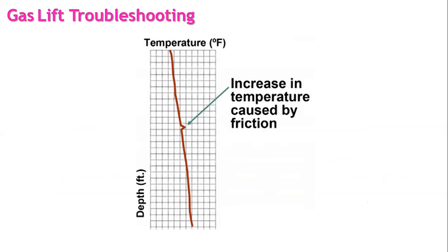We run a production logging, or basically temperature logging, and define where is the point of any problem, a gas leak, or probably a point of unexpected injection of gas in a point we are not considering. So here we have a temperature log.